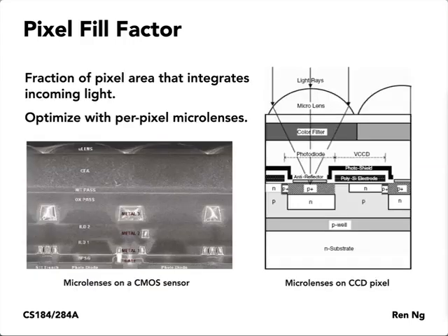Okay. Now, as I showed you a couple of slides ago, here's a cross-sectional electron microscope picture to go with this. Let me orient you to this picture here. So this is the photodiode area. This is a cross-section of a CMOS chip here. This is the photodiode area where the photoelectric effect will happen.